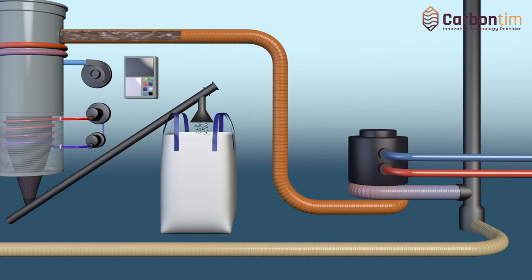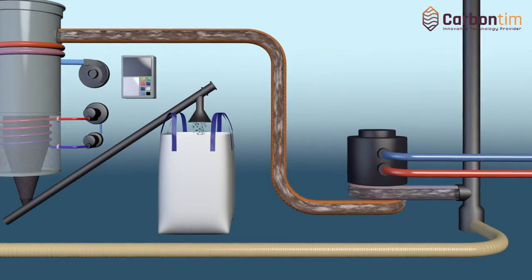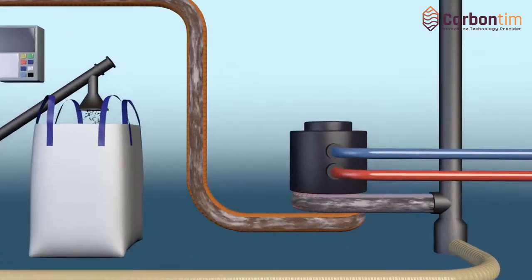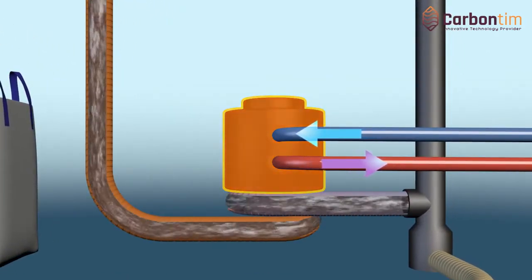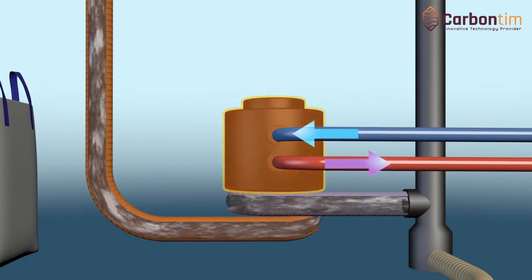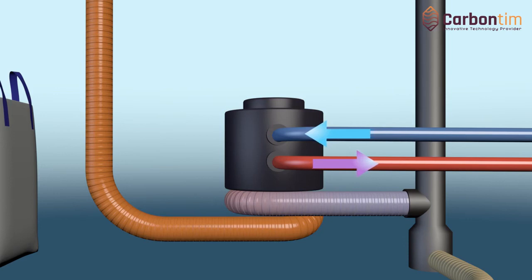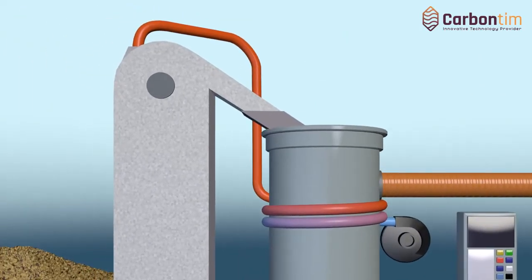Heat generation. The flammable gas has a relatively low calorific value, so the best way to make use of it is by conversion to hot water. Pyrolysis systems with productivity from 300 to 1,000 kilograms per hour can supply district heating networks with a maximum capacity from 1 to 3 megawatts respectively. The yield of flammable gases depends on the type and quality of the processed biomass and the expected characteristics of the carbonized biomass.